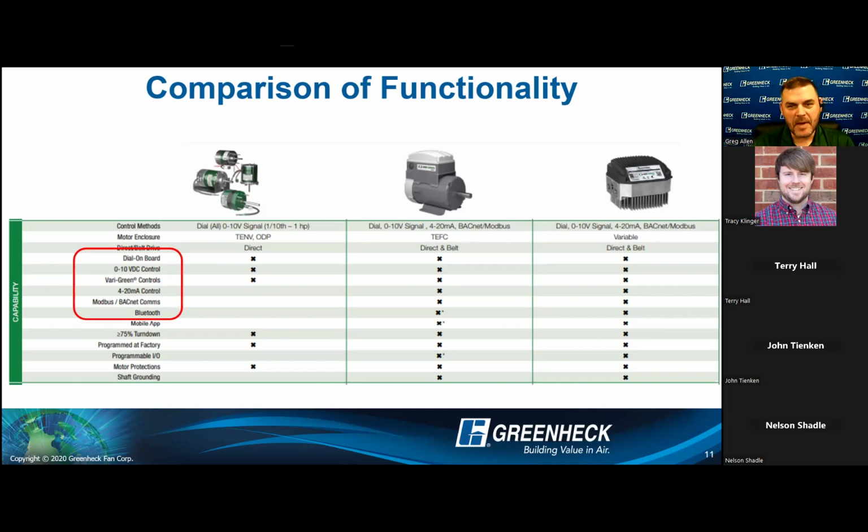I just highly recommend going back, looking up the installation, operation, and maintenance manuals or the submittal sheets that come with those different products to make sure that as a designer of systems, you are seeing both controller and controlled and making sure they can speak.